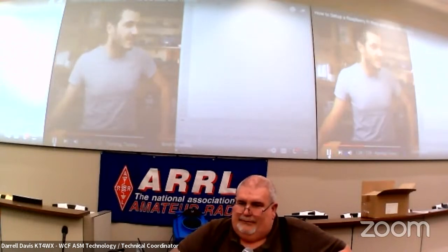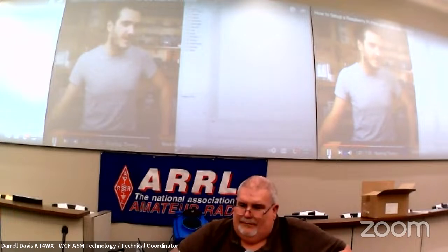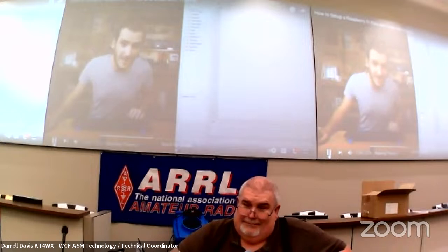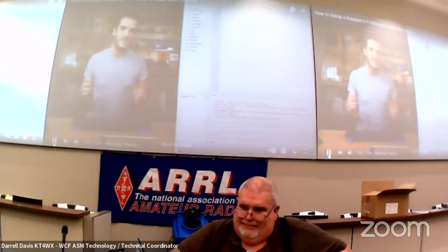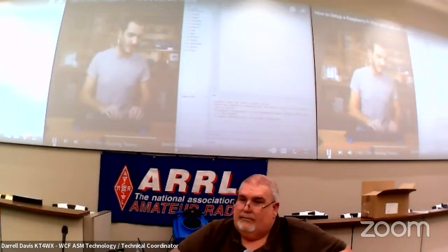One last thing that makes life a bit easier is to go to View and Files. This will show us our file tree on the left. So we have the local files on our computer and the files that are on the Pico. And we are ready to go. I have the REPL down at the bottom here. This is the interactive Python REPL that's running on the Pico. We can actually execute some live code.